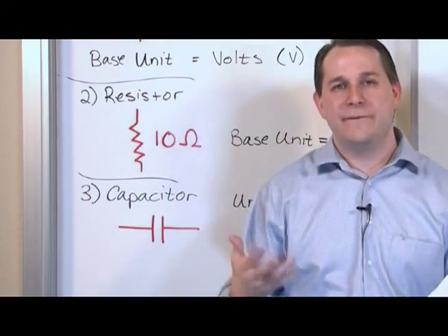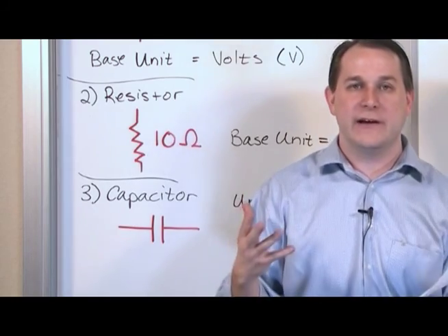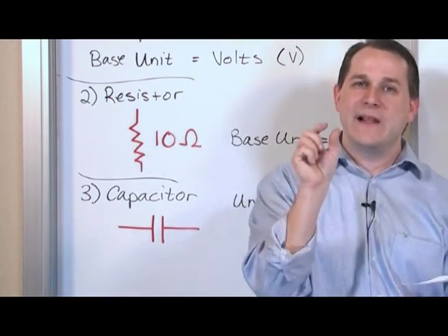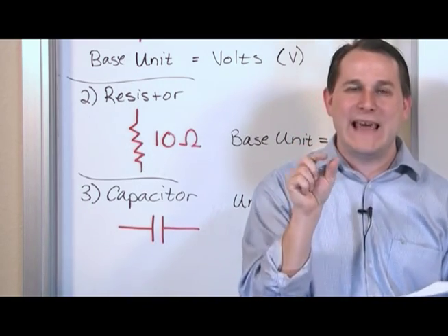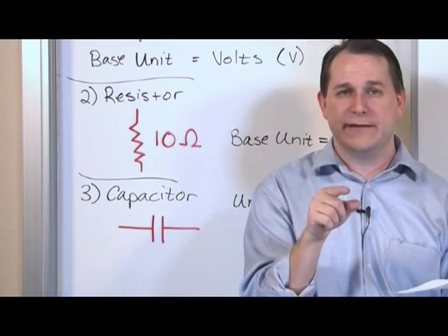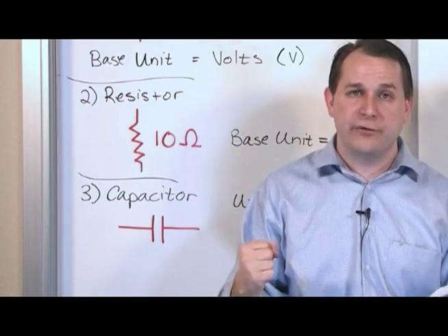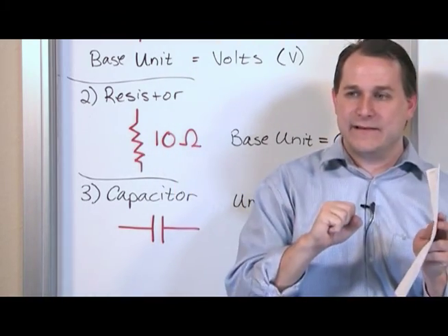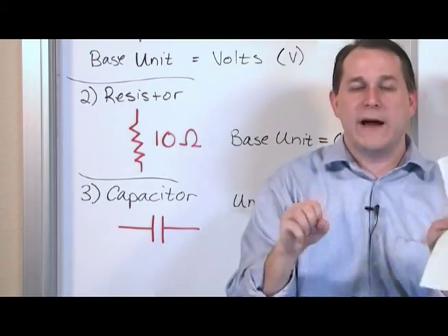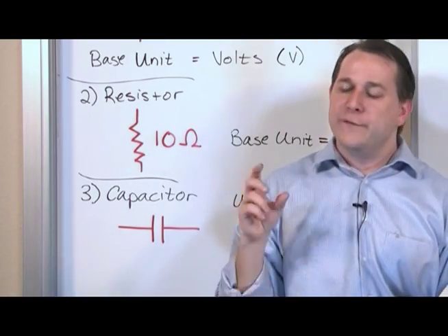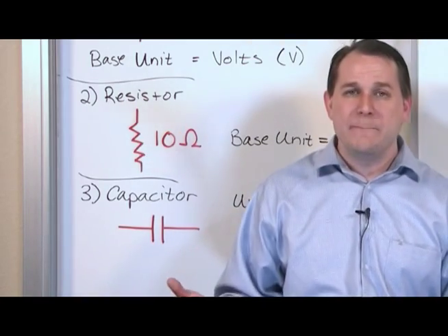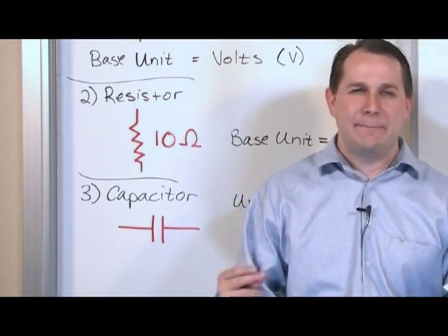The reason you have to accumulate that much charge in a capacitor bank to fire a flash is because that flash bulb is actually a little bit of gas inside of a bulb, basically, and it takes a lot of electricity to jump in there and cause that gas to ionize, for the electrons to jump around and release all that white light. So if you hook your battery directly up to the flash bulb, nothing will happen because there's not enough. You need it to happen instantly.